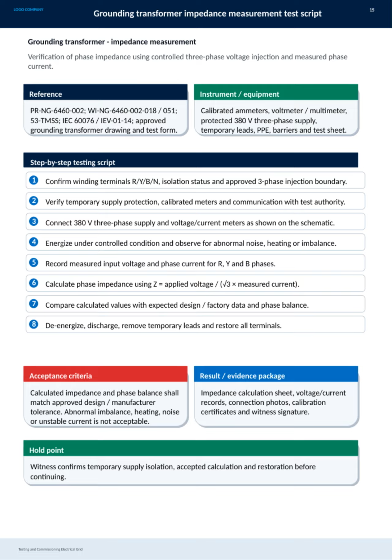After the test, we de-energize, discharge, remove temporary leads, and restore all terminals. The crucial acceptance criteria demand that the calculated impedance and phase balance fall within the manufacturer's tolerance, with no abnormal signs such as imbalance or unstable current.